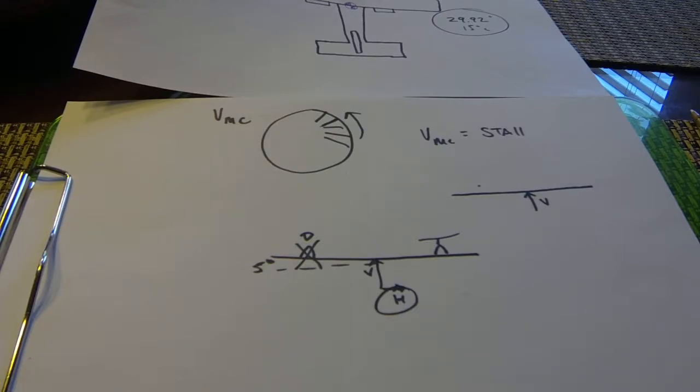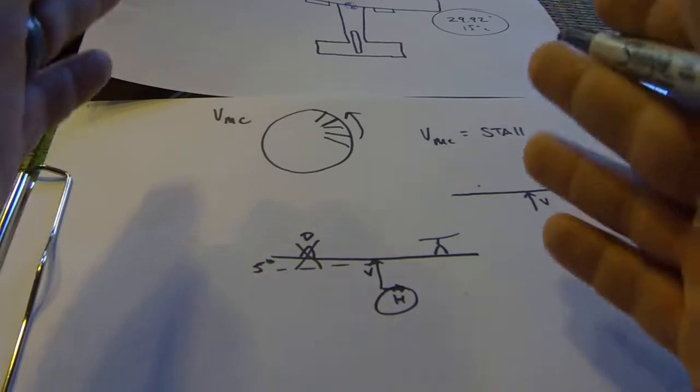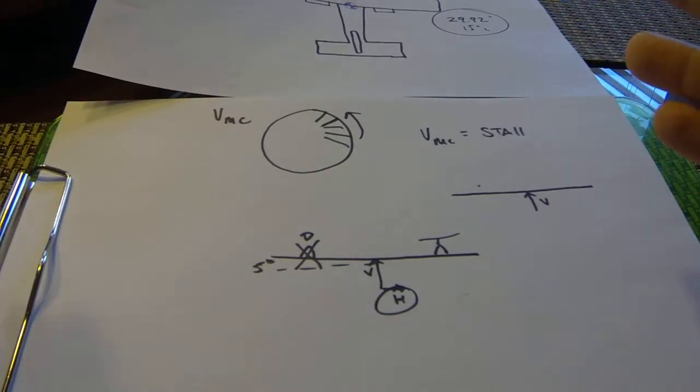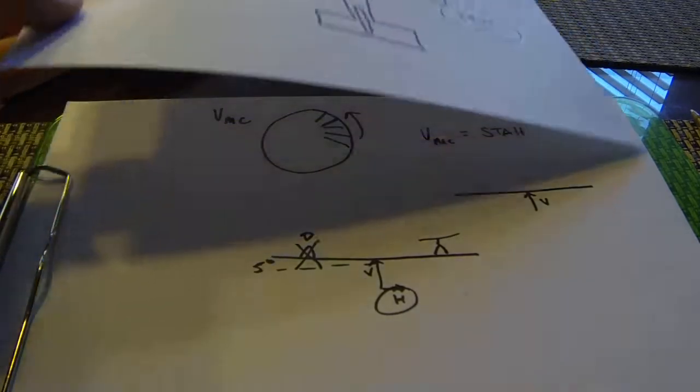When we have one engine inoperative, creating drag is the last thing we want to do. So generally, we want to keep the gear up. However, just realize that putting the gear down could lower VMC due to the directional stability factors that the gear may provide. Flaps up versus flaps down.